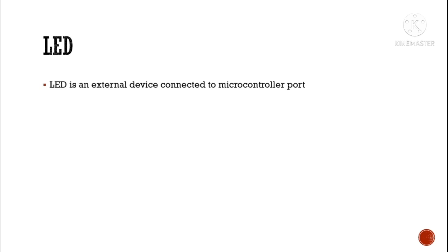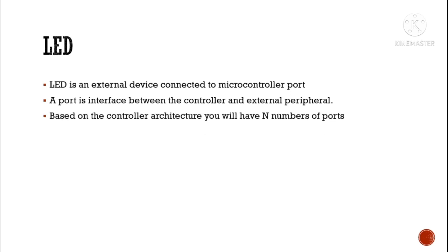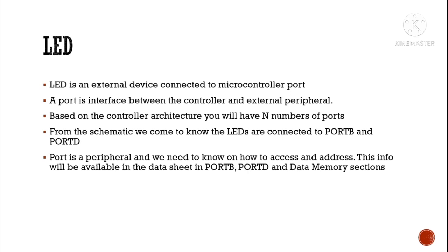An LED is an external device connected to a microcontroller port. A port is the interface between a controller and external peripherals. Based on the microcontroller architecture, you will have n number of ports. From the schematic, we know the LEDs are connected to port B and port D. A port is a peripheral and we need to know how to access its address. This information is available in the datasheet, in the port B and port D and data memory sections.